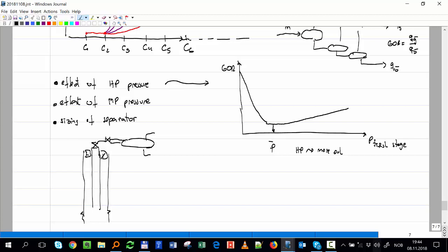If we increase that pressure, what will happen with the equilibrium point? It will decrease. Even though we're recovering more oil, that has a counter effect on the rate that I get, because here I have my IPR, and then I have the TPR.